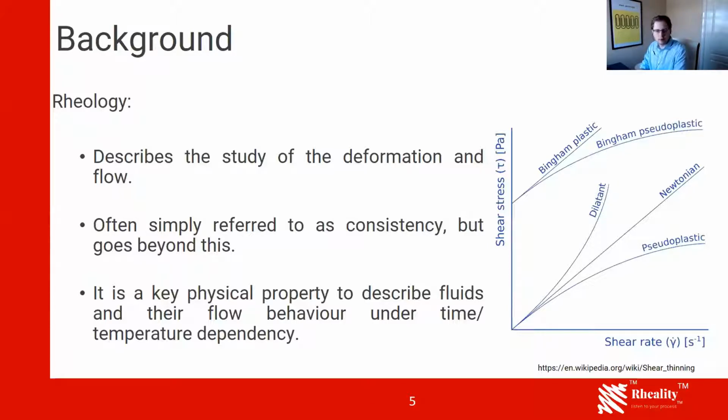You might have heard people often talking about consistency or viscosity, but rheology goes way beyond this. If you look to the right side, and this is a very simple, generic picture taken from Wikipedia, we can see rheology is unlike viscosity or consistency measurements, which are single point measurements. It gives you a curve, and we can then have different models or mathematical ideas behind it to describe how these fluids behave. In the simplest case, a Newtonian fluid, where the relationship between shear stress and shear rate is linear, but you might also have things like a Bingham plastic, like toothpaste, which sits solid in your tube, and you need to bring in some energy to make it flow.